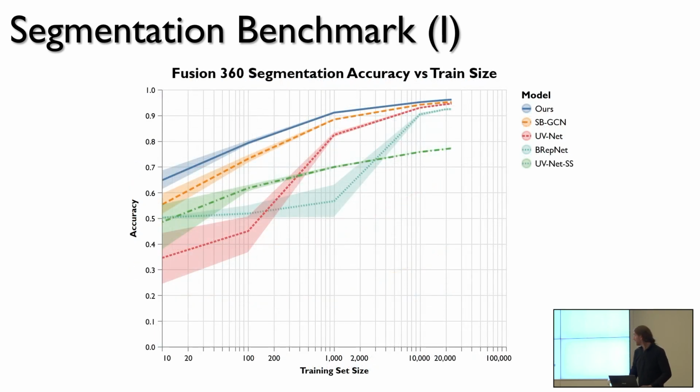And finally, I'd like to highlight the green curve here. That's the only other prior self-supervised BREP learning approach that uses contrastive learning instead of this geometric self-supervision. And this striking dissimilarity in performance emphasizes to me, at least, that using the geometric self-supervision is really important to getting this sort of performance. Somehow learning to be a CAD kernel means that you have to encode all of the relevant information in your embeddings versus just learning to distinguish between similar graph structures.